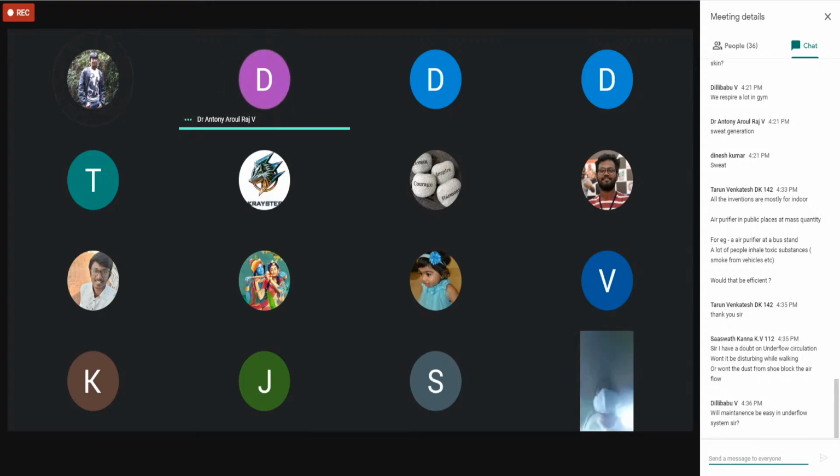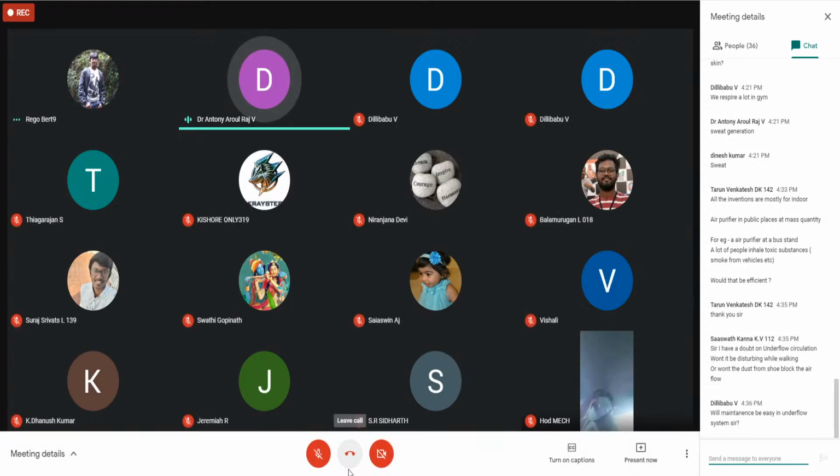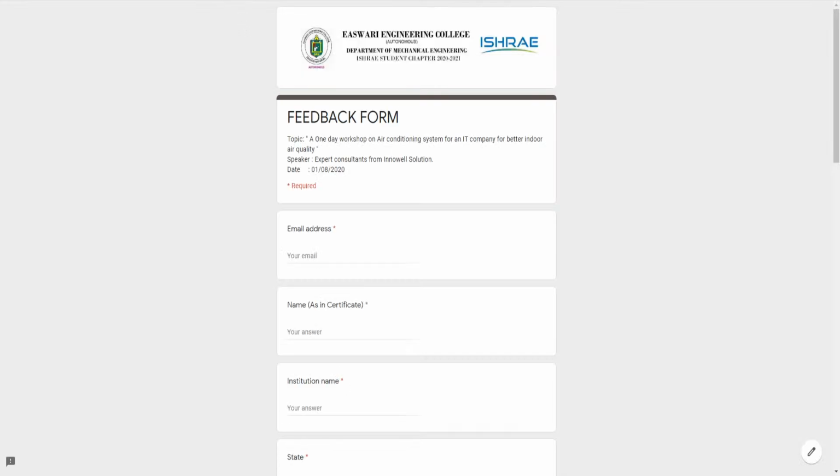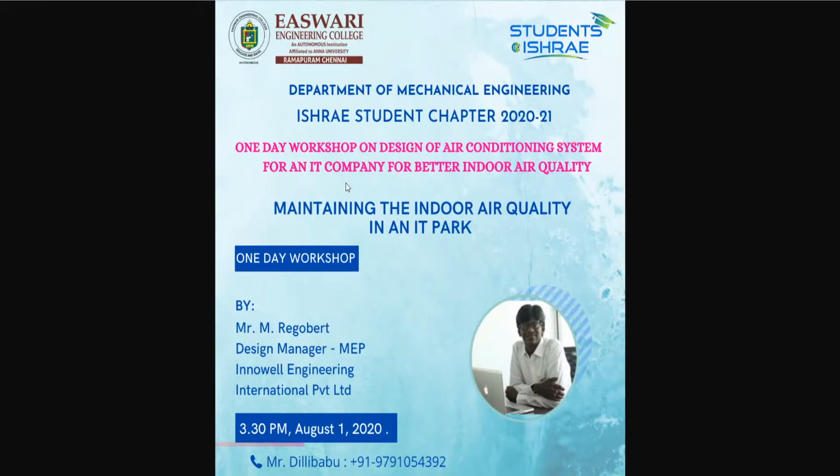Sir, I have a question. Yes, sir. This radiant cooling system, won't it produce condensation in highly humid places? Exactly, sir, this is a very good question. In a radiant cooling system, we will not operate a chiller at 7 or 12 degrees. We are going to operate at a 15 or 20 degree chiller. That is one thing, and we will have a very limited fresh air quantity.